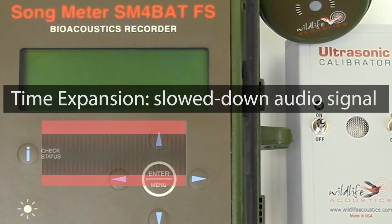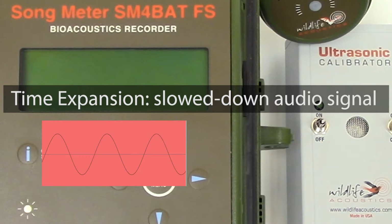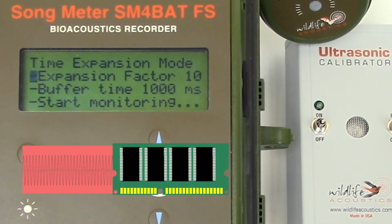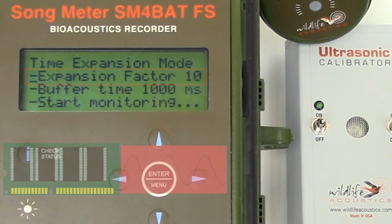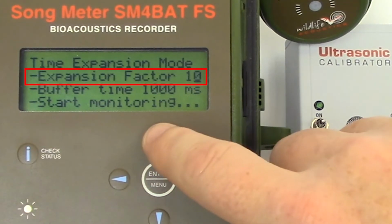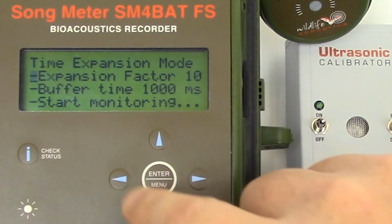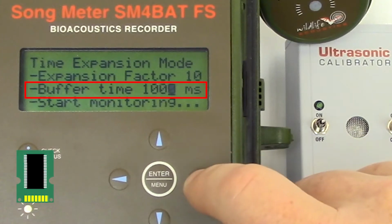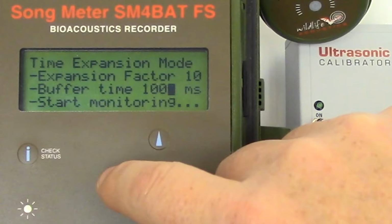The SM4BAT can slow down an ultrasonic signal so it can be played back at a lower frequency that is audible to the human ear. This is done by recording a signal into a buffer inside the recorder and then slowing the audio down for playback. The expansion factor parameter allows you to select whether the recording is slowed down by a factor of 10 or 20 times. The buffer time sets the record playback buffer size. This is adjustable from 50 to 5,000 milliseconds.